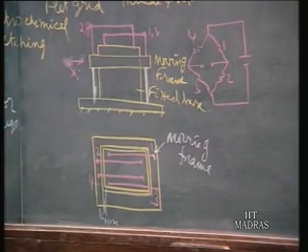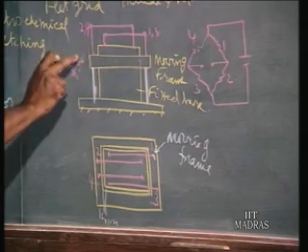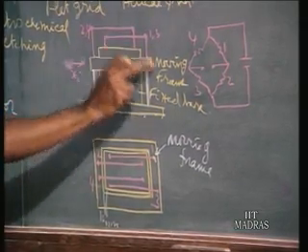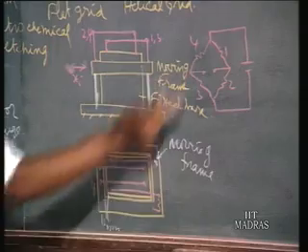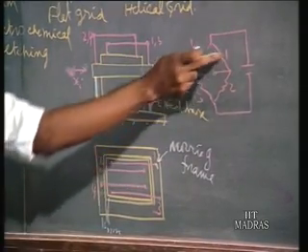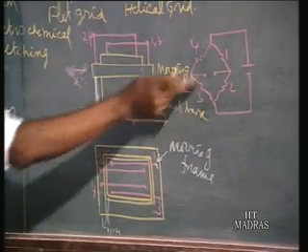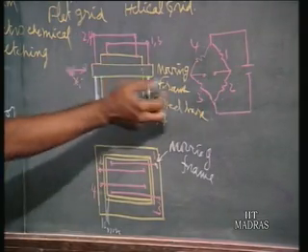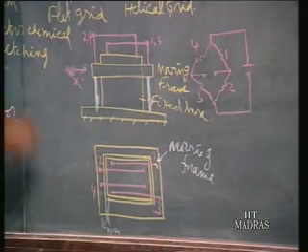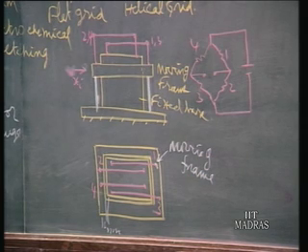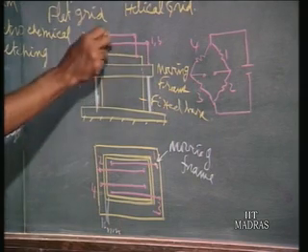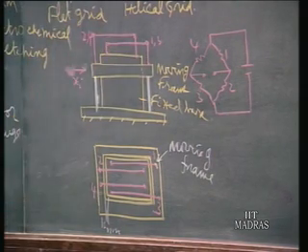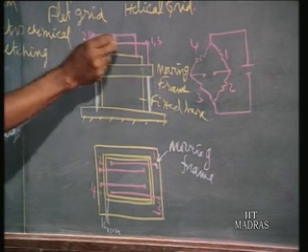The tension in wires 1 and 3 will increase, and the tension in wires 2 and 4 will decrease for this motion. So 1 and 3, which are connected in a bridge like this, where the tension is increased, are opposite arms, and where tension is decreased is the other pair. So you will find all 4 arms active, it is a full bridge. In 2 wires tension is increased, in the other 2 wires tension is decreased. So the resistance increases in one opposite pair and decreases in the other opposite pair, and you find a full bridge effect there. That's how the 4 wires work, and that's why it's called an unbonded strain gauge. The strain gauge is made up of 4 wires.